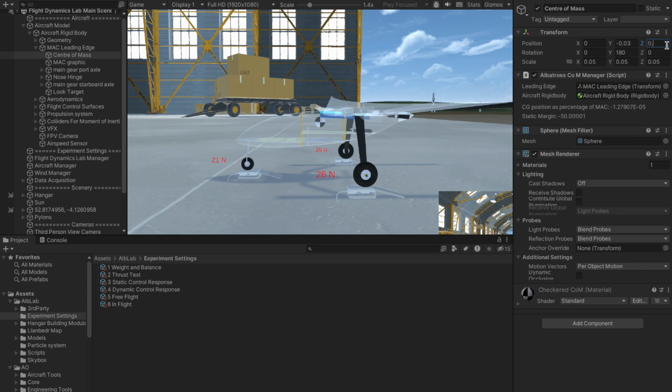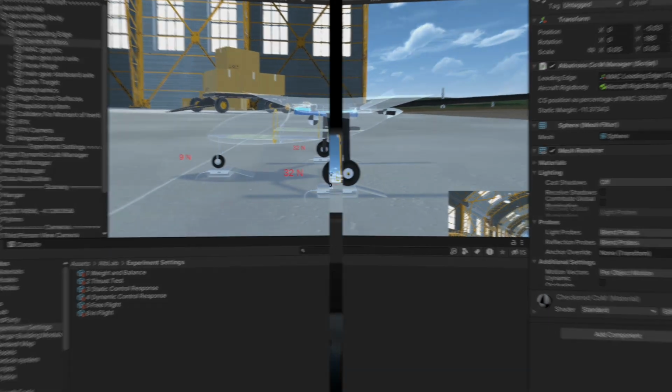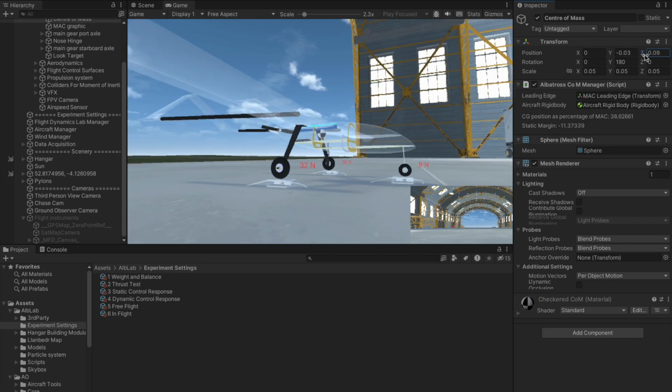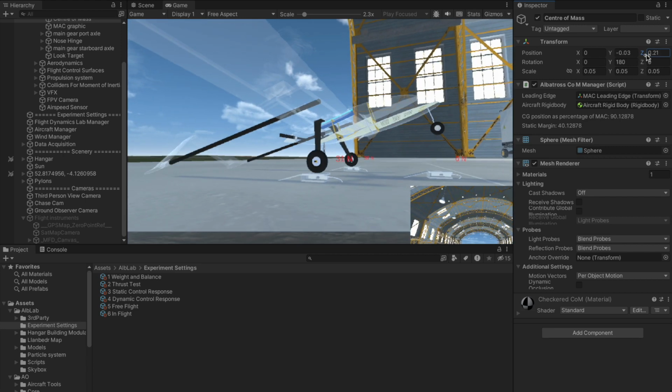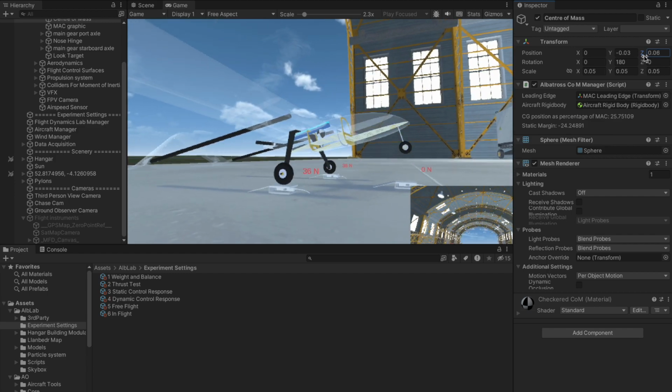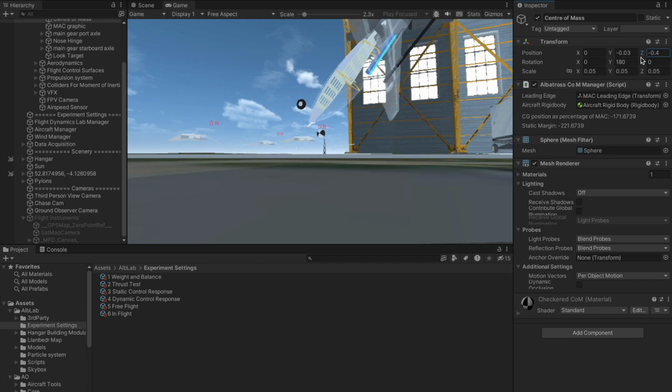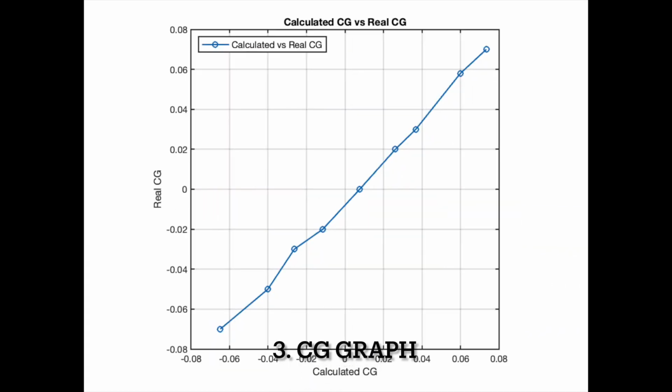The Albatros was positioned on 3 separate scales to gauge the mass distribution. With known landing gear positions, determining the forces makes it easy to calculate the moment arm and the CG, which varies from the initial test values. Adjusting the CG position along the longitudinal axis affects how the weight is distributed across each landing gear. By adjusting the test CG position incrementally, the total moment is calculated by multiplying the measured load and the corresponding moment arm. The total moment and measured load allow us to find the measured CG.